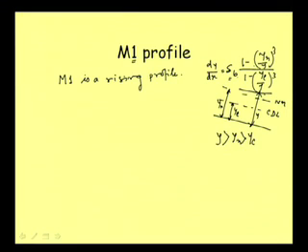That we emphasized when we were doing the derivation of the gradually varied flow, perhaps we remember that, and that is why this SB is also positive. And this means that dy/dx, that is the change of y with respect to x, say depth here is y, here is suppose y1, then the change of y with respect to x, x being this direction, is positive, means it is a rising profile. So this will always be positive. If it is negative, then only it will be a falling profile.